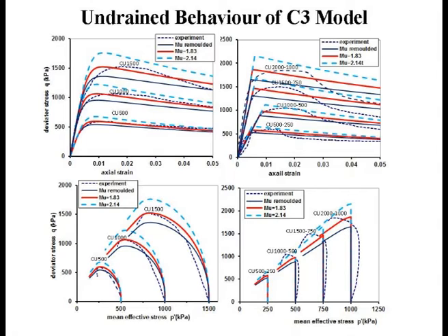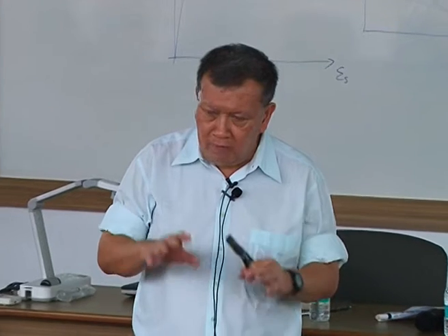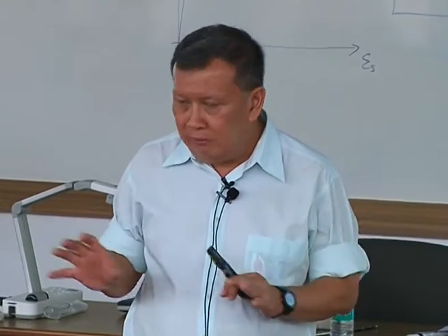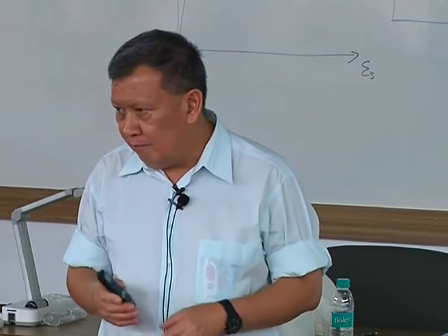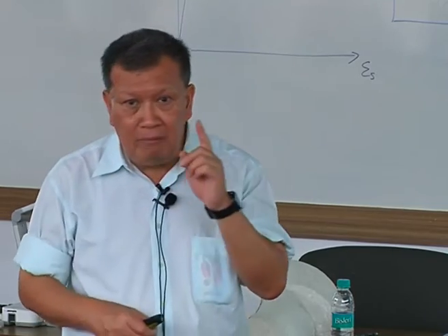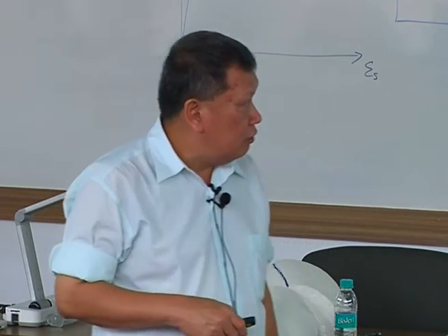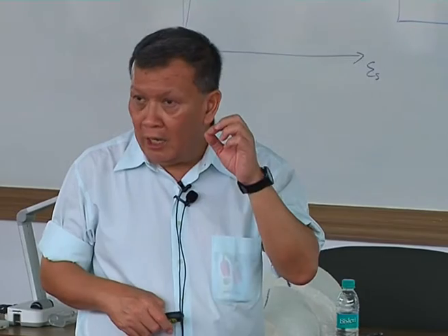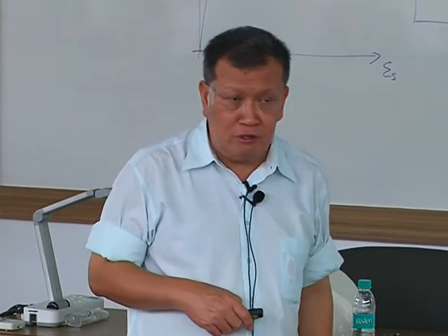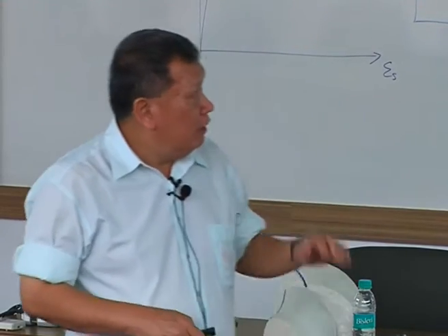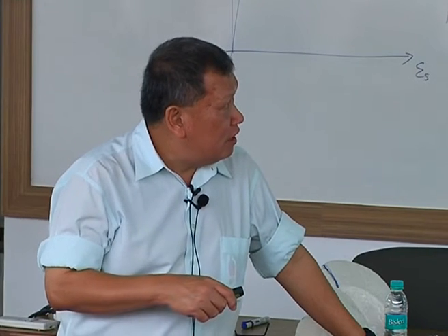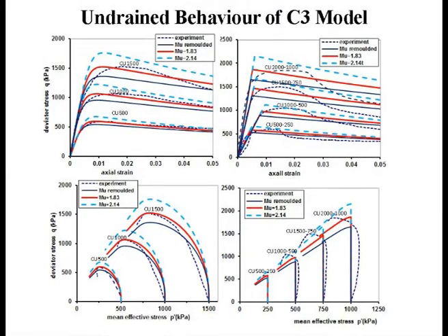And what you find is that none of the existing models, the soft soil model, the hardening soil model, Cam clay model, modified Cam clay, original Cam clay, Mohr-Coulomb, whatever, in all these standard programs, none of them will model this kind of structured behavior. And if you ever hit a structured soil, one thing you can use to see whether the soil is structured or not: if you look at the stress strain curve, they all have a peak strength and then come down. You see that? Peak strength and come down.